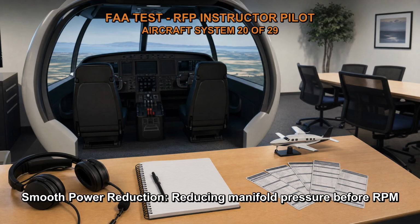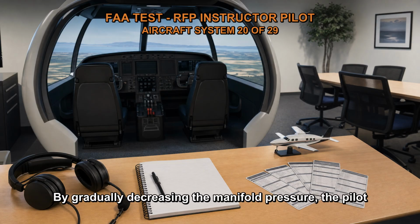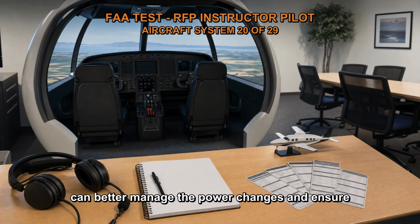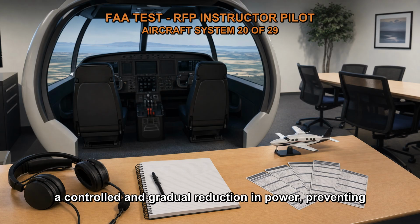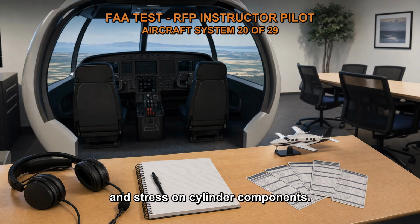Smooth power reduction. Reducing manifold pressure before RPM allows for a smoother power reduction sequence. By gradually decreasing the manifold pressure, the pilot can better manage the power changes and ensure a controlled and gradual reduction in power, preventing sudden and potentially damaging fluctuations in engine load and stress on cylinder components.